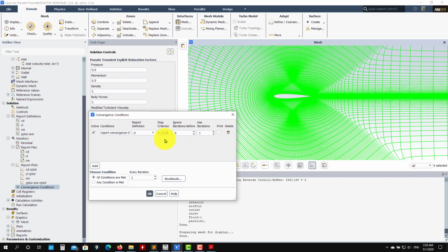I usually like to use this value, and then do not compute in the first 10 iterations. And to reach this convergence, just use the last 10 iterations, okay? If you put 100, you will need to compute those statistics over 100 iterations and see that it's not oscillating more than this quantity. So 100 is a large value. I like to use 10/10. In my personal experience, I have found that these values are okay. Sometimes they can be really low, so you will never reach this. But again, you can play with this one.